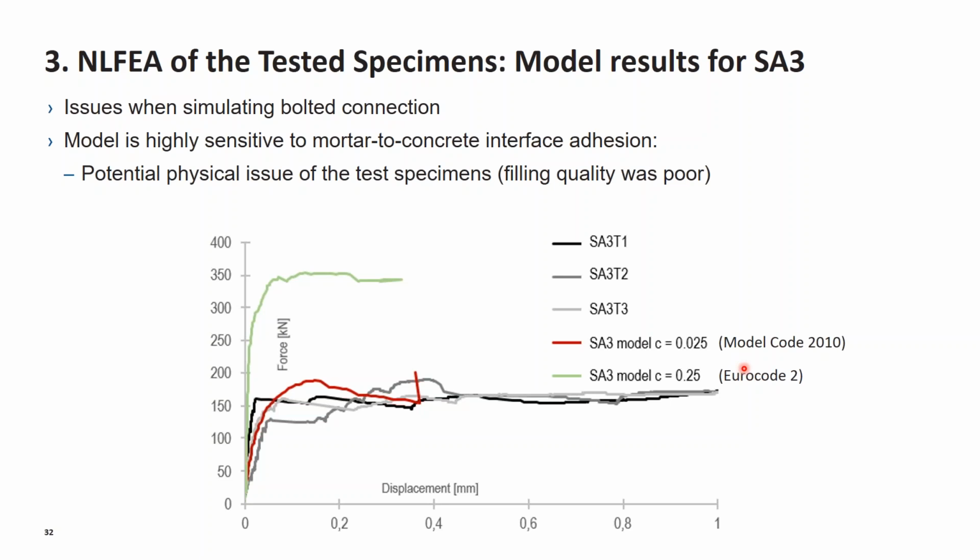For the interface model, it is required to define interface stiffness, and I used the Diana 10.5 version. I didn't have the automatic definition of this interface stiffness, and I used the general relationship that is provided in the documentation as a guideline, and the models were defined with those values. Okay, thank you for this clarification, Dan.